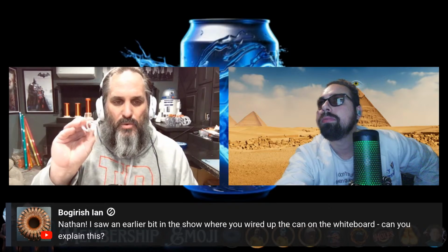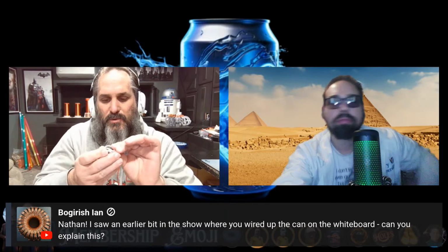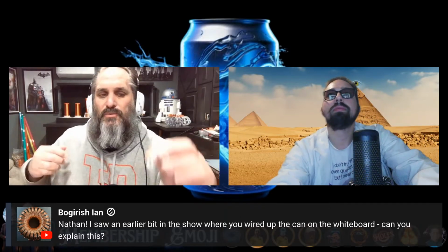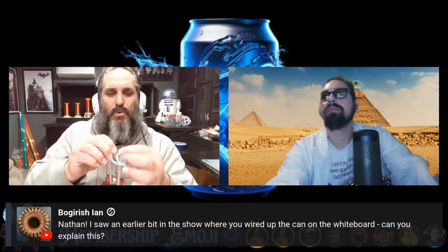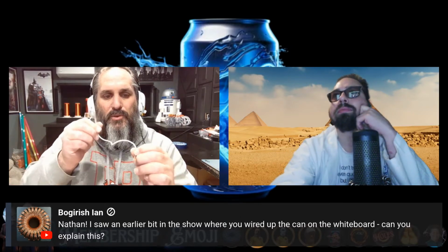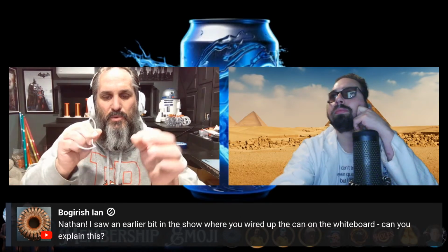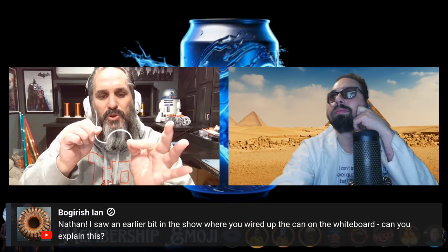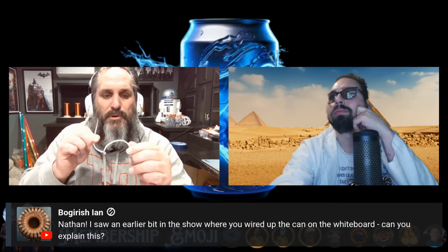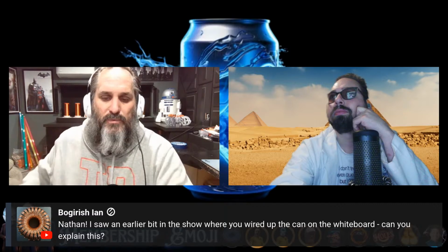And what that's doing is it's supposed to create more amps in that winding. One of the connections from this goes straight to the can, and the other one goes to your full bridge rectifier. The one that goes to the can, you just hook another clip on that, and that goes to the other side of your full bridge rectifier in order to rectify it.